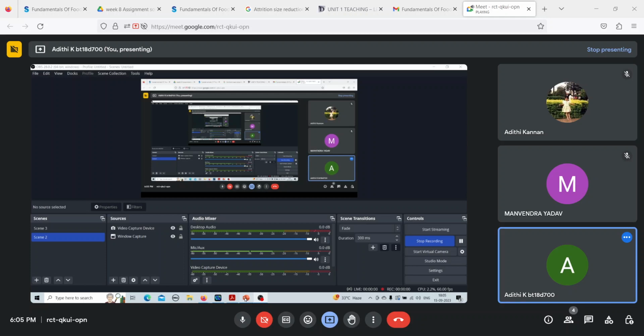What you mean by angle of nip is this particular angle. If you draw a tangent here, at the point at which the particle is touching the first roller, and you draw a tangent at the point at which the particle is touching the second roller, then when the two lines intersect, that angle is known as the angle of nip, and that is always equal to 2 alpha.